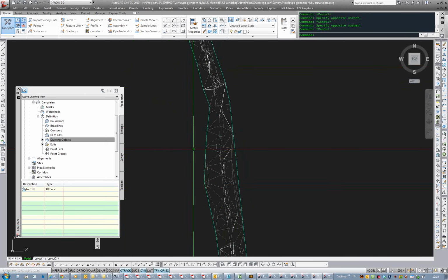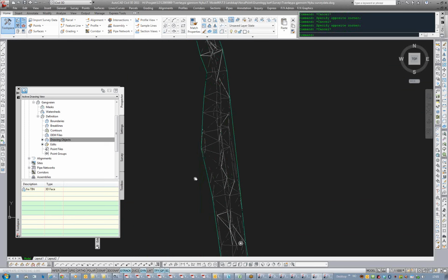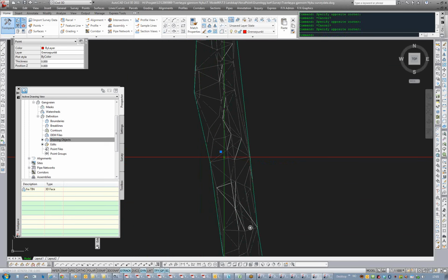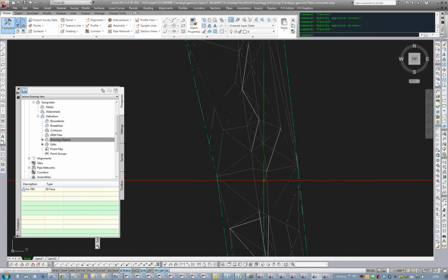Okay, and it would only pick the wall, right? Yeah, if you set it point to point, it's only going to pick points, but you want to make sure your OSNAP is set to node. Node. Right. Yeah. Okay, so these are property lines.